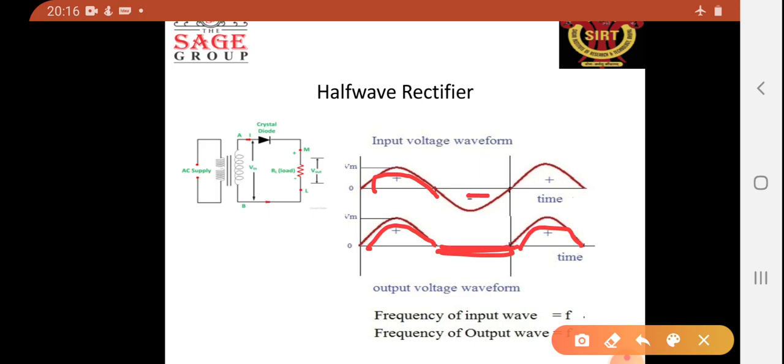So we can say that this is a DC, because in AC the current flows in both directions, positive and negative, but here the current flows only in one direction. But we know that DC is constant. This is not pure DC. So the output of the rectifier is not pure DC. It contains some components of AC also, due to which it has fluctuation behavior. So now we have to filter out the AC components from the output of the rectifier circuit.